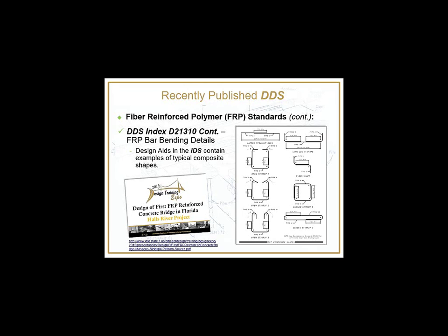require a little different configuration than traditional steel reinforcing, because of the limitations on the number of bends that the manufacturers can provide in any single bar. So there's a lot more lapping of these U-shaped and other bend-shaped bars. So that's just something to be aware of when you're detailing your bar bending requirements, which most commonly are going to be where your sheet pile cap, and maybe in the future